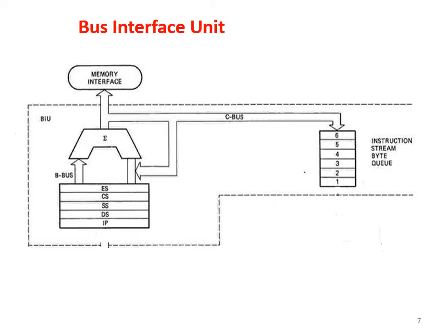But what is the maximum capacity of 8086? It can give only addresses of 16-bit or data of 16-bit, and its register capacity is only 16-bit. How can you transform this 16-bit address into a 20-bit address? That will be done by this summation block. And each of the segment registers and your 1 megabyte of memory is divided into different logical segments. There are specific sections for data, code, etc.